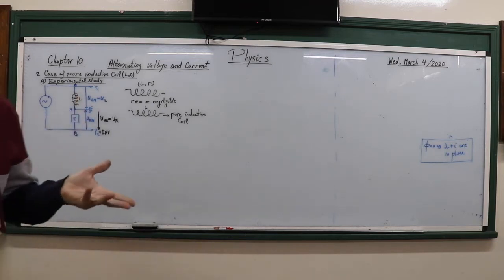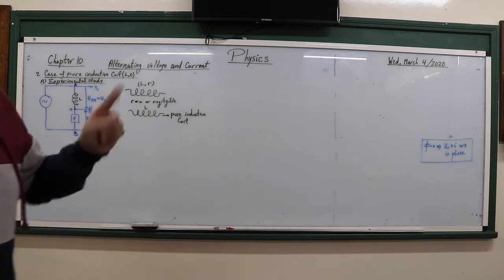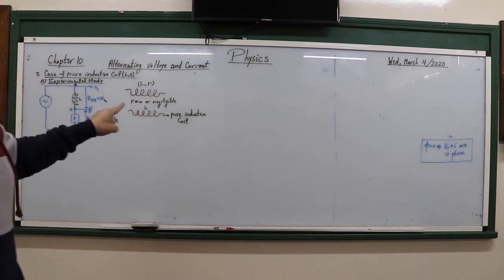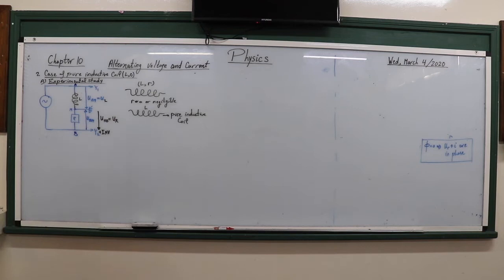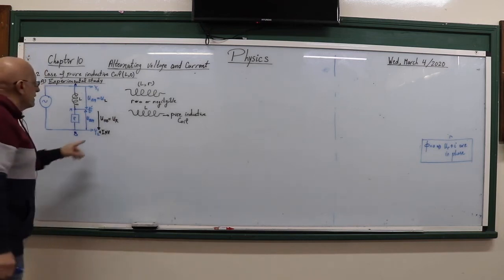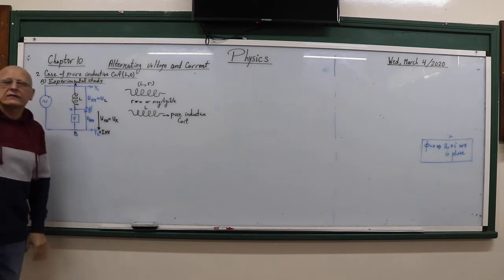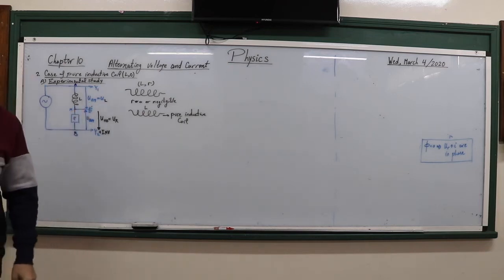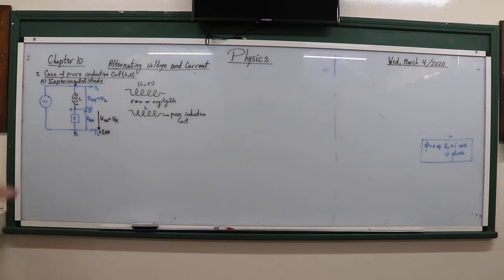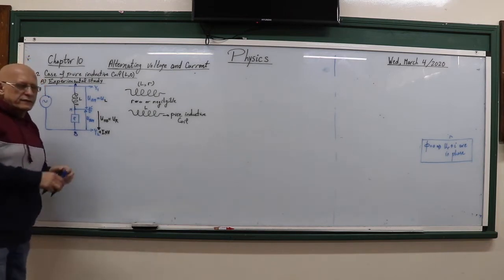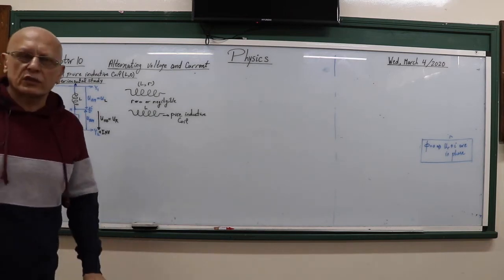So what should I do? I press the invert button that reverses the voltage of the second channel so that UMB and UAM have the same direction. Now, what do we observe on the screen of the oscilloscope?